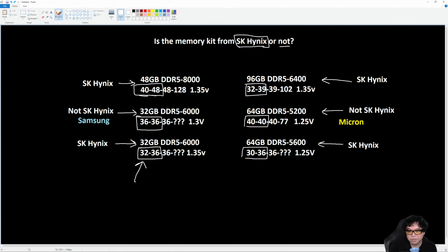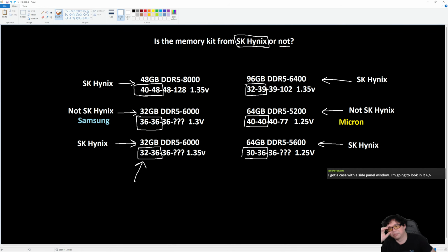Dust on the floor. That's what your dust filter on the front intake of your case is for. That's another reason why I don't believe in aquarium computer towers. I go basic front to back airflow: front intake, rear exhaust, and the top is where the radiator goes. If you're doing an AIO, it always goes on the top, and exhaust out the top. Get all that hot air out of the system.